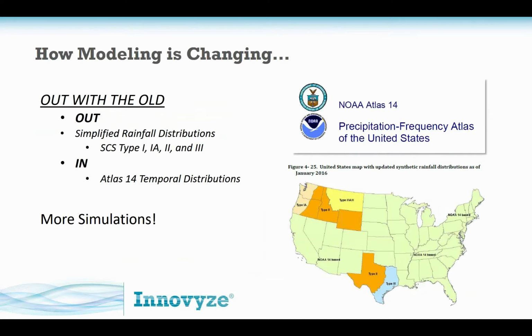In this case, NOAA over the last couple of years has brought in new temporal distributions and specified them in specific areas. I think when I was looking at Florida a while ago, the majority of the counties here in Florida have more than one rainfall distribution associated with them. So geographically, it's probably much more precise than what was measured back in the 50s through daily.